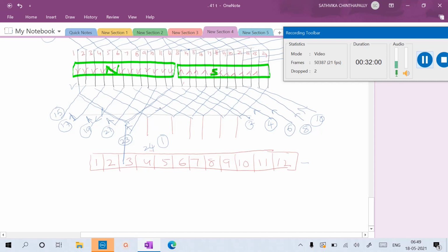Then you can see here, it is connected to the fourth one, fifth one, sixth one, seventh, eighth, ninth. Similarly, you connect the remaining ones to this one. So these are the 12 conductors, you connect them. Now slot 1 is connected, and the remaining 8, 9 we are going to connect here.